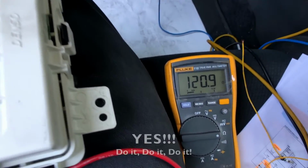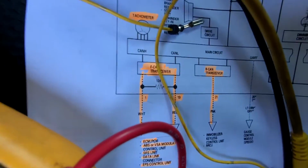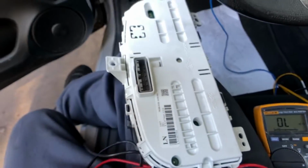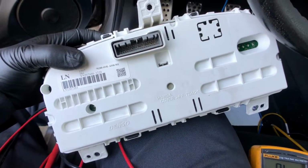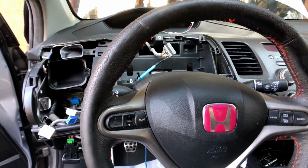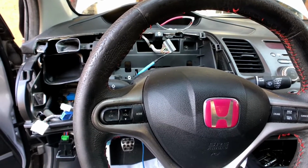I don't know, do I start unplugging modules that are in line with that F-CAN and see when my communication comes back? Because the resistance on this gauge control module assembly is within specs. I don't know, I might stop the video here and have you guys give me some input. So I'll see you guys when we're onto something.